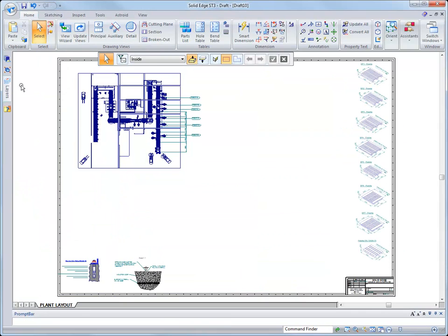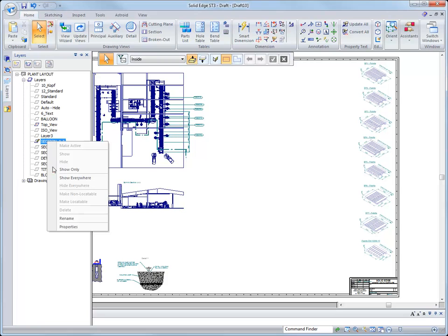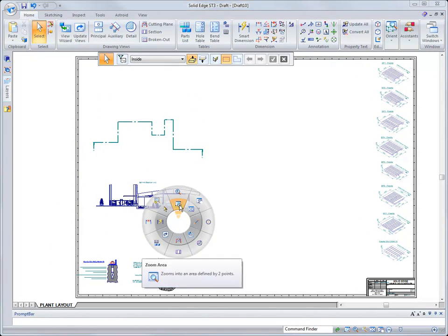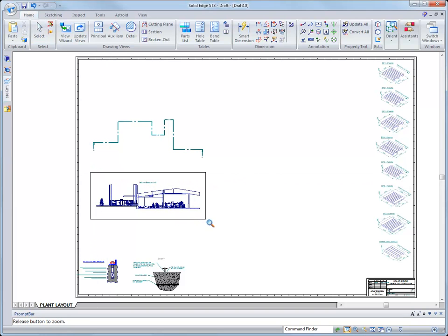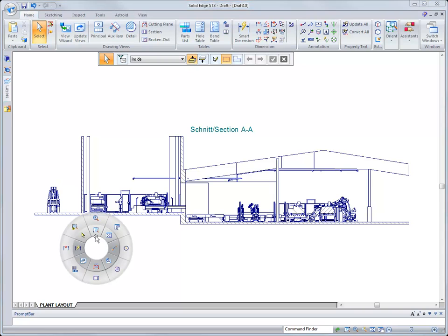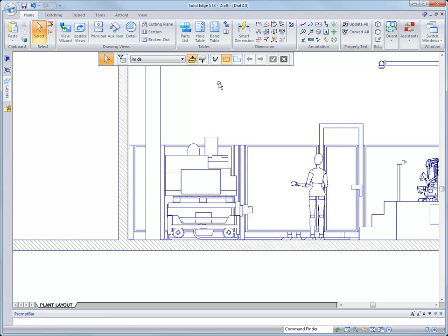Now let's move to the final section view. Large assembly drawings typically are used to communicate positional information, hence full component details aren't needed. The detail we are working with is the draft quality view, meaning that it is very lightweight. Solid Edge understands this, and with our draft quality views, huge performance gains are seen, but full dimension support is still available.